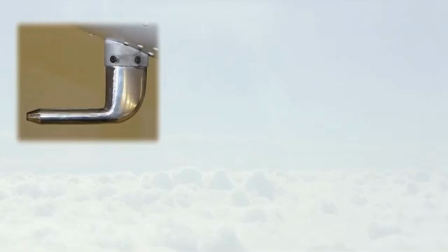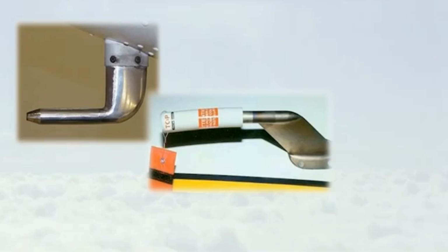The following checks of the airspeed indicator and pressure supply system should be made before flight. If they are fitted to your aircraft, pressure head covers and static vent plugs must be removed and stowed aboard the aircraft. The pitot tubes, holes or slots in the static heads and or static vents, should be checked to be free from obvious obstructions such as insects.